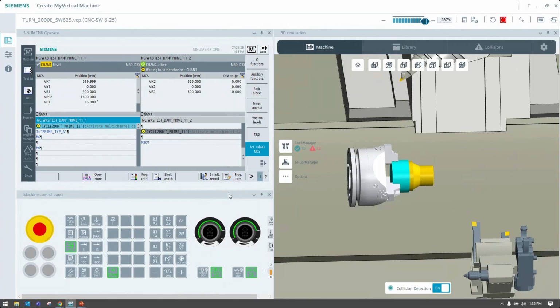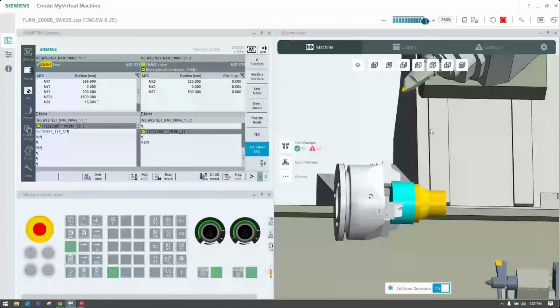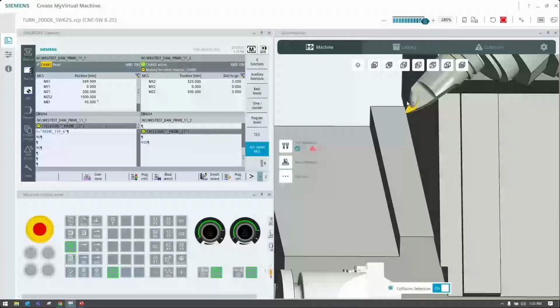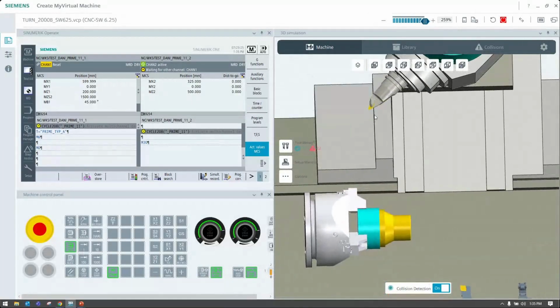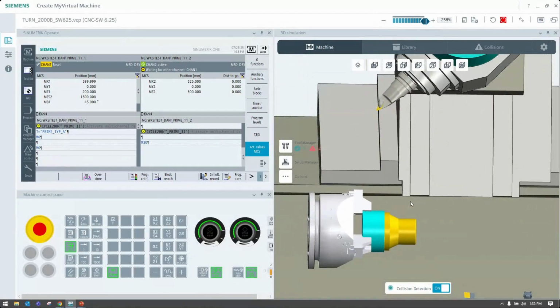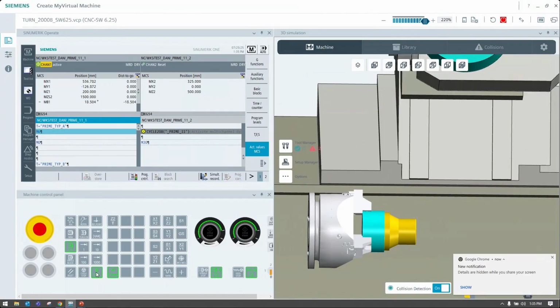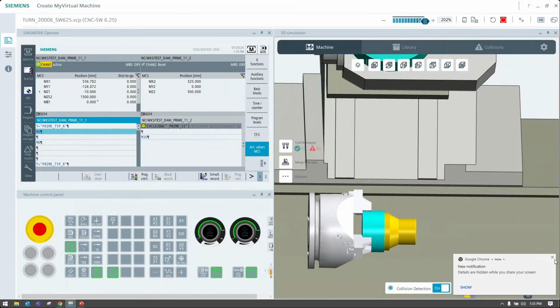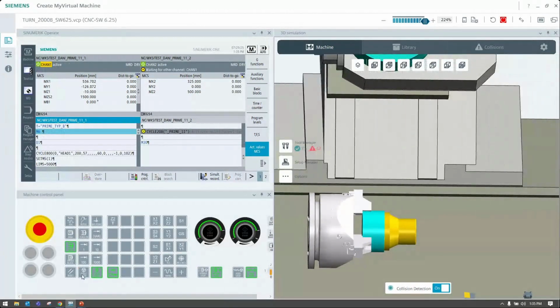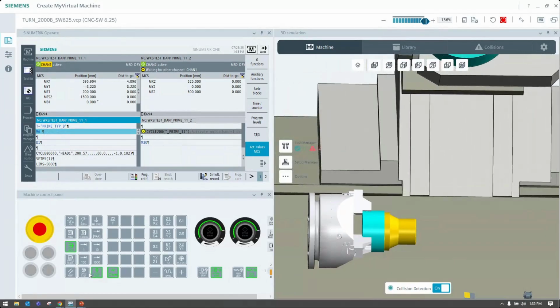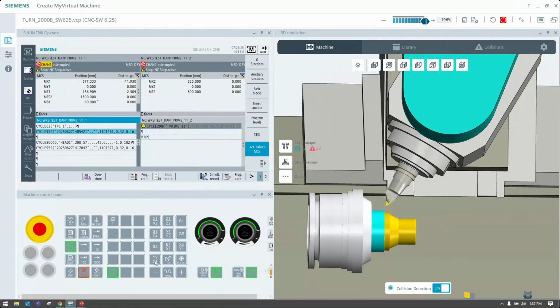Yeah, that sounds like it's coming from firsthand knowledge. Yes. Because we learned about this because we're like, oh, we got to pull it backwards. I've been around CNCs. I don't need no cam system or no cycle to tell me what to do. So I just literally programmed it and did it the first one. I can show you here when we get the other tool. I was like, okay, well, I got this tool. They say I got to go away from the chuck. I put it in there like this, and I just did a straight line backwards. And yeah, she just took the insert right out.